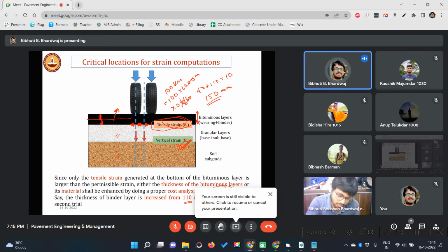So it is almost 100 square meter, and if you multiply by the width of the road, 3.7 meter, it will be around 7,000 cubic meter for 100 kilometer. Just because you were too lazy to make it and check whether 120 was okay or not. So anyway, we will make it 130.